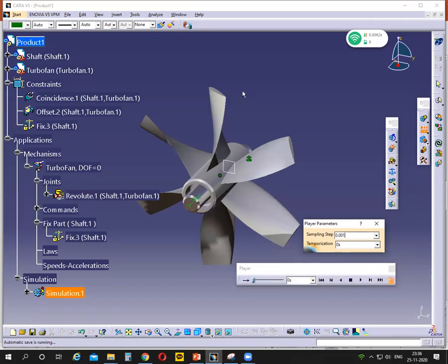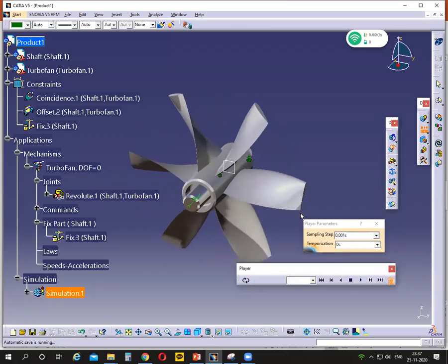Click here, select this one, simulation player. For which simulation, we have to select this one, and click here and select the step size, 0.001 second, and play that. This arrow means only one time, so you can rewind many times and play. So slow, very slow, right?